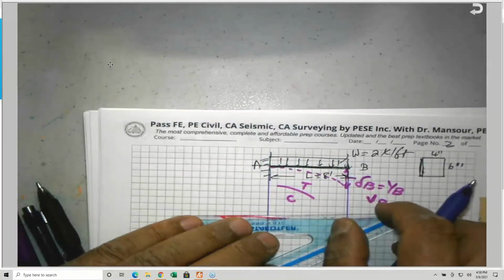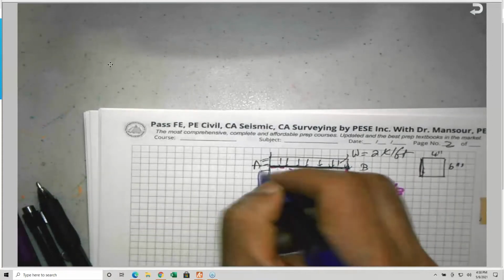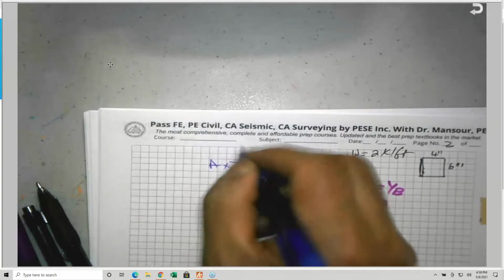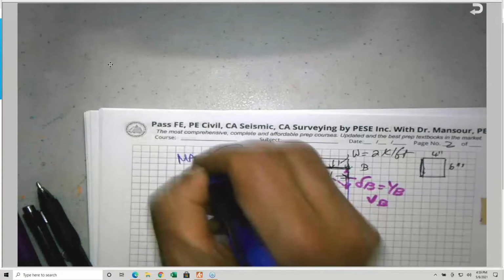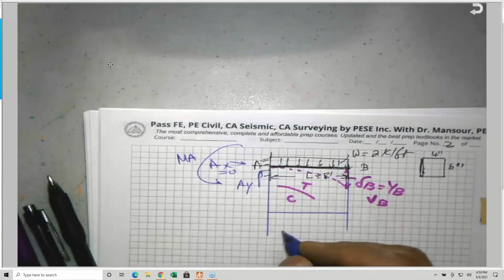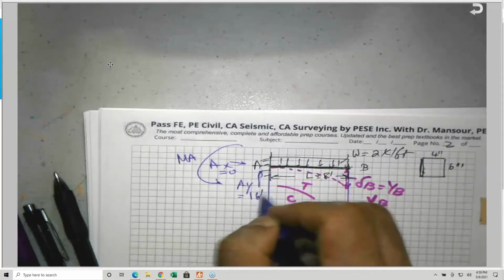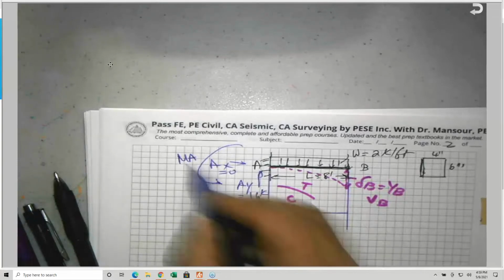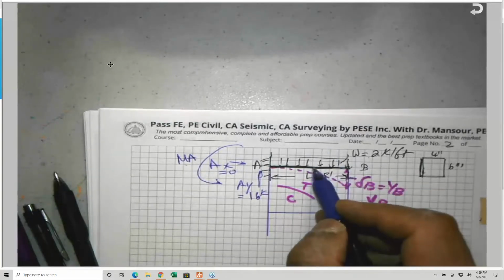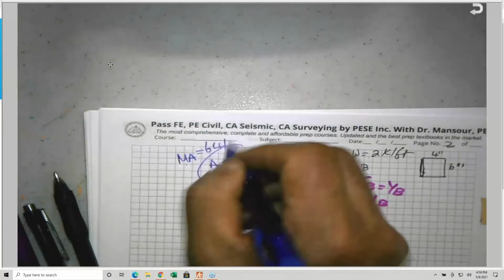You'll find that for the shear, basically I have a reaction here, A sub y, and we have A sub x, and we have the fixed-end moment, which is M sub A. The A sub x is obviously equal to 0 by inspection, and A sub y is 2 times 8, which is 16 kips. The moment is 2 times 8, 16, acting at the centroid. The centroid is at 4 feet. 16 times 4 is equal to 64 kip-feet.